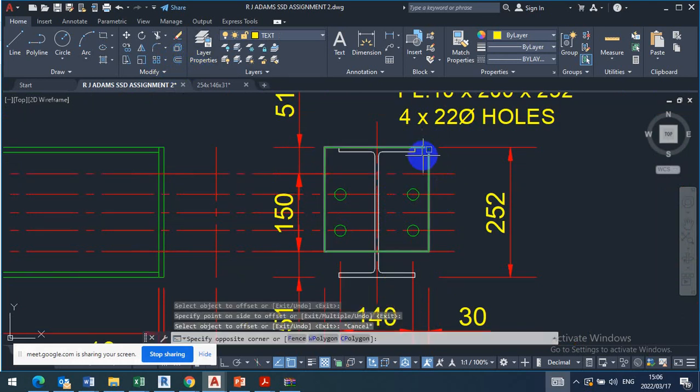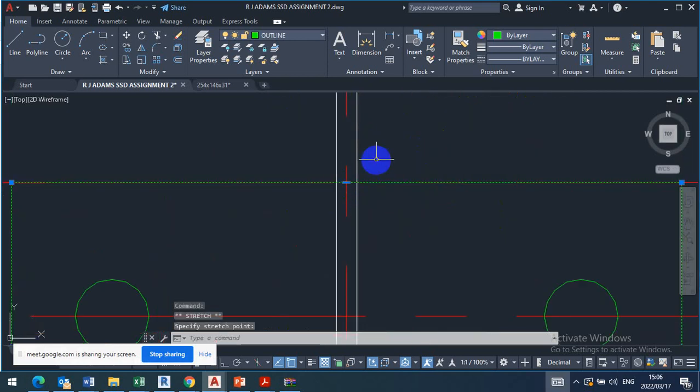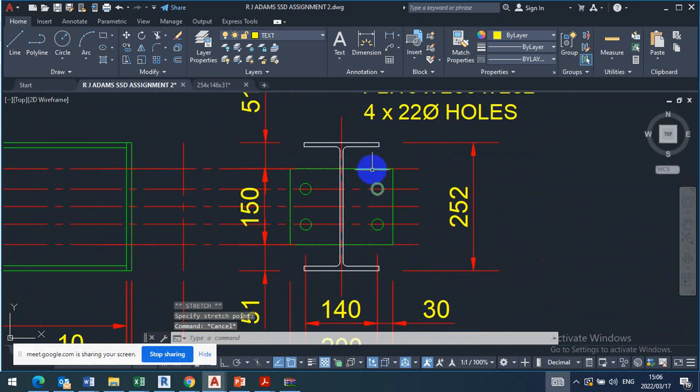If we want to maintain the edge distance of 40, this one also saves material because you're not going to cut a lot. Can you see? Then check here, what's this we said from here to here? What was that, 70, right? When we checked the gauge one, G1 of 70, meaning offset 3.5, enter, which is offsetting this one here, 3.5, 3.5.